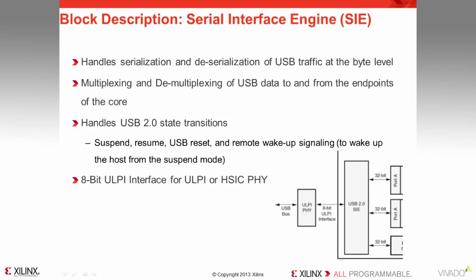8-bit ULPI interface or HSIC interface is the PHY interface on the left hand side. So on the right hand side, it receives data either through control or register logic and through DPRAMs. And on the left hand side, it gets transferred to the 8-bit ULPI interface.